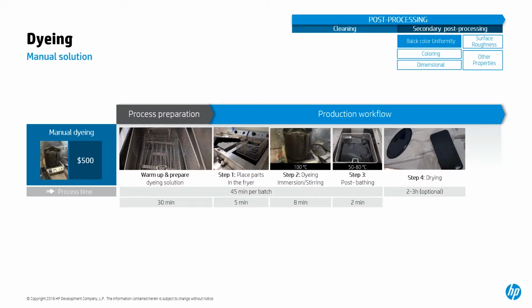He just wrote back and said, how about to enhance the color? Is there a way to enhance it? Yeah, for example, through coatings. So a varnish could be applied, for example, or a wax on top of the part, and all those are going to enhance the color and get more vivid colors. Or chemical polishing could be another option as well, where you can get glossier parts.